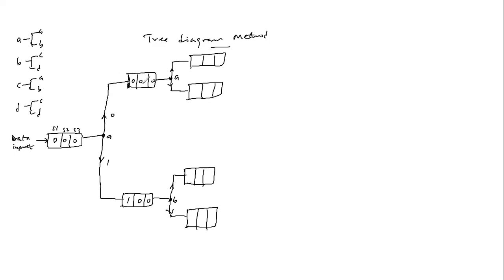And now recall the branch again. So here the initial state is all 0. So when it is 0 is emitted here, 1 is emitted here, so it goes on to 0, then the others are shifted. Here it goes on to 1, then the others are shifted. Now in this case, 1, 0, 0 is the initial state, 0 is emitted here, 1 is emitted here. So when a 0 is emitted here, then this 1 is shifted, and then the 0. So when a 1 is transmitted here, then the 1 is shifted, and the 0. So this is how we go on and on, okay?